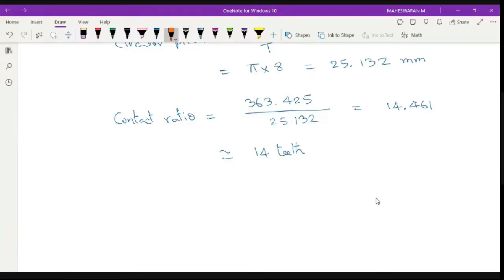When you have a higher number of teeth in contact, your rotational velocity and friction will be more, and you can easily transmit power, right? But at the same time you have a sliding velocity, which is disturbing. With more contact, the rubbing velocity will be higher. So even though a large amount of power is transmitted, the gear wears out quickly. Can you get it?